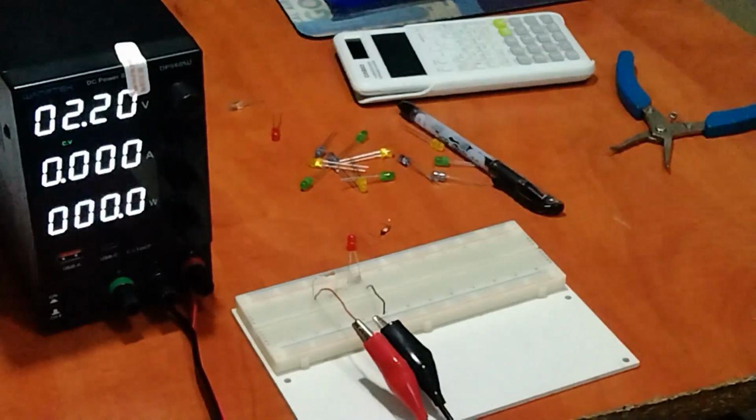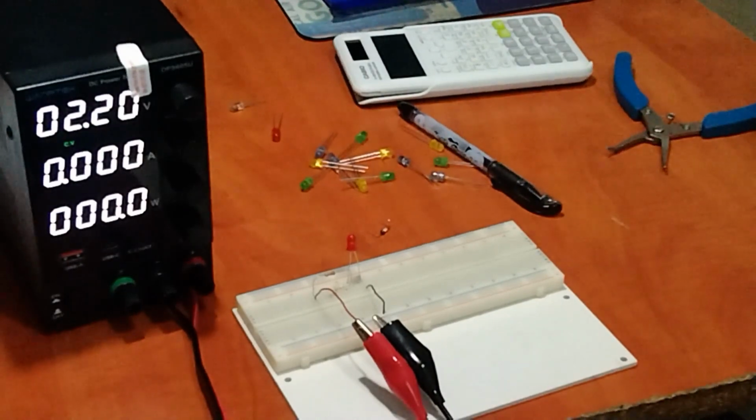You see that your LED doesn't even shine. Why? The resistor is too big. The bigger the resistor, the lesser the current that is allowed to pass. So it is important to sit down and calculate the value of a resistor, the wattage, and then you can place the right resistor for the right circuit.